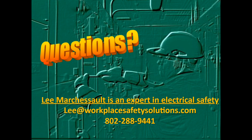Can you wear steel-toe shoes, or is the proper PPE composite toe shoes? Yes, you can wear steel-toe shoes. They make EH-rated boots with steel toes. I wear them all the time. The electrical rating on boots is basically where the rubber hits the road. It's the sole of the boot. So if you're outside in the grass, electrical rated boots don't do anything for you at all. It's only where you're inside and standing up. So steel toes are not a problem with the electrical rating.